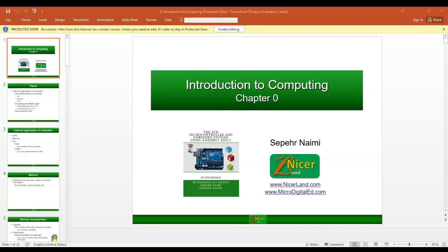Its organization is written in two parts: the number of locations into the number of bits of the data. Like here, 128 locations are here, and every location has 4 bits of data. Here, 128 is 2 raised to power x, where x is the number of address lines we have for this memory. The access time would be the time it takes to get data from the memory when the memory is commanded to give an output.